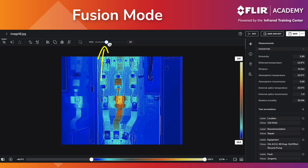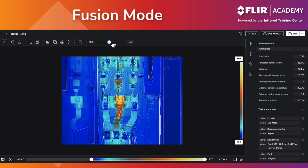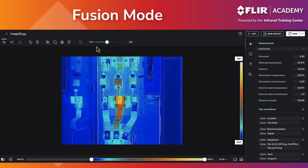When MSX is enabled, this slider can be used to adjust the intensity of the visible light overlay. Slide it all the way to the right for full MSX. Sliding it to the left will reduce the visibility of the MSX overlay.